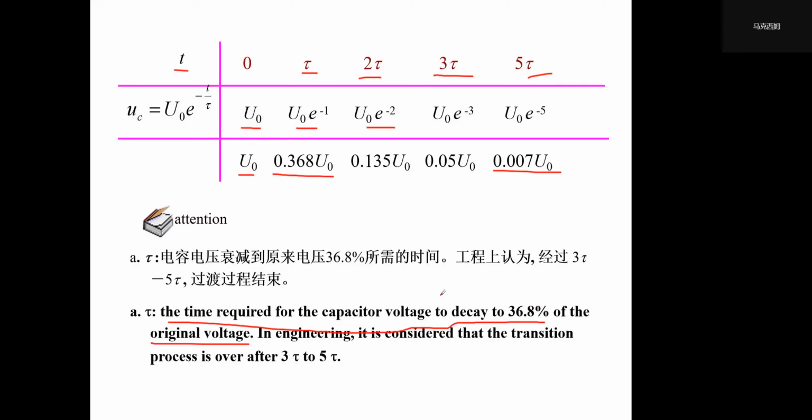Then we mark that time, and we have the number of the time constant. But this is only for this first order linear system. For higher order systems we have different methods, but the basic thinking is almost the same.